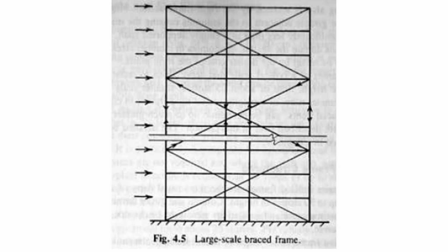Large-scale braced frame is another way of providing bracing in braced frame structure. This can be seen in Figure 4.5. However, the presence of either small or large-scale bracings may obstruct the view. Thus, as a solution, the braced bay shall incorporate a long wall and partition, lifts, stairs or service shafts.